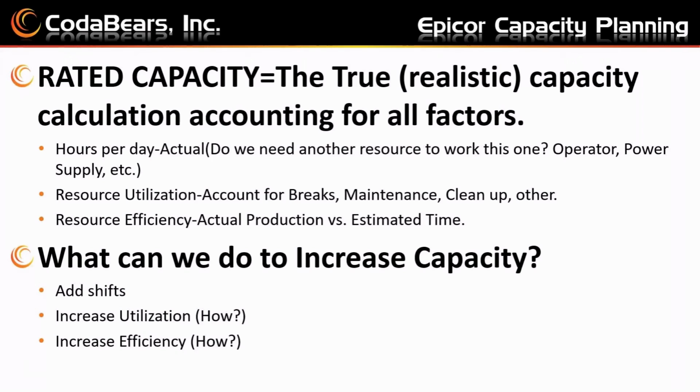And also the efficiency. So there's always, hey, this is capable of achieving 60 pieces per minute, but what's your actual production efficiency? Many companies will also put a fudge factor in of, say, 90%, 85%, whatever works for your company. And as you see the truth over time, those factors can be adjusted in your rated capacity such that you get closer to the actual value.